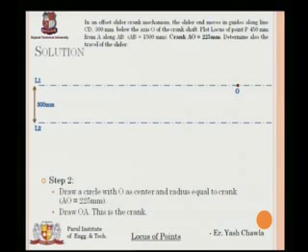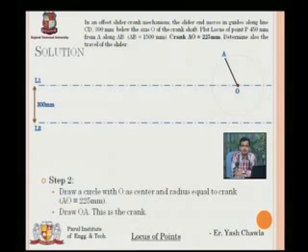Now what is my next step? Now I have my O, so I will draw the crank circle, as we did in the previous question, because I should know how far my crank is and how it will be rotating. So I will take my radius as AO, that is 225 mm, equal to the length of the crank, and I will draw a circle. Now, with the crank circle, I'll take any position and draw my crank. AO is my crank that will be rotating.